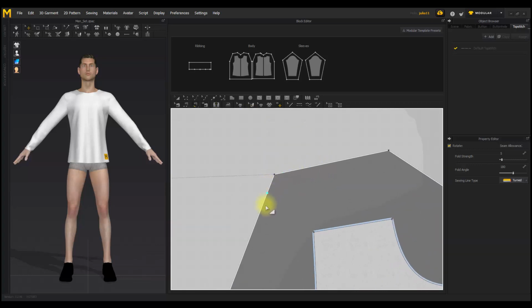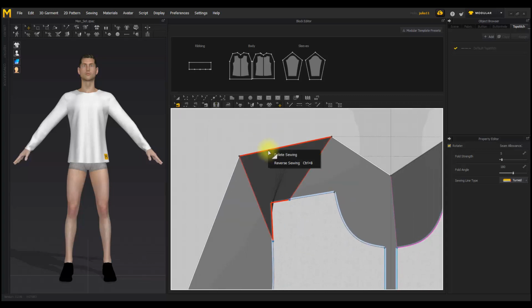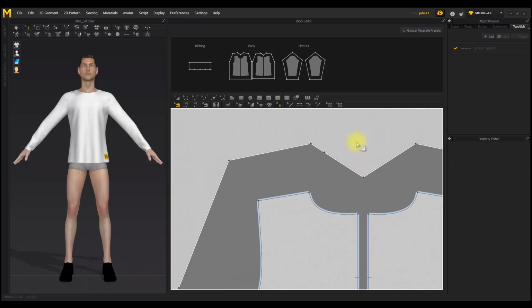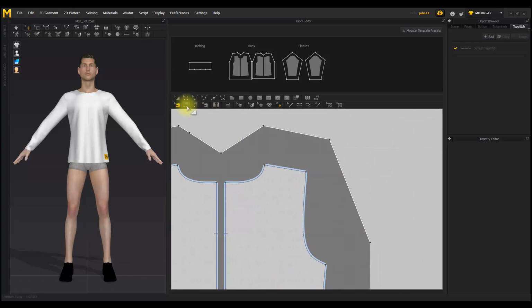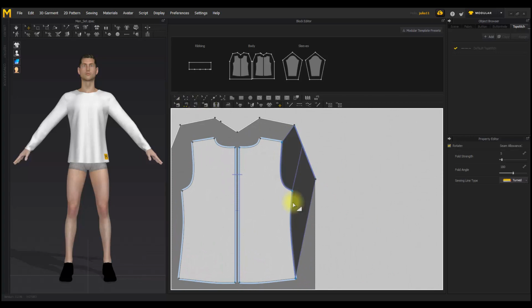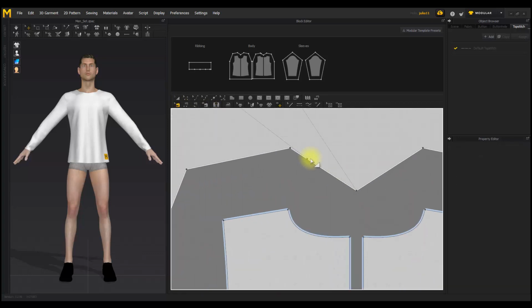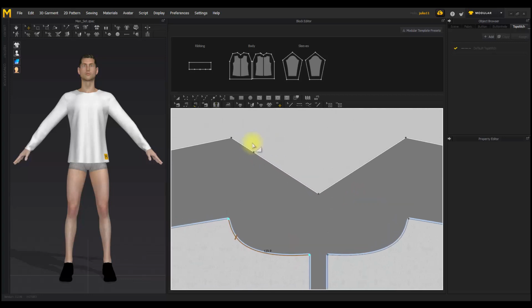Please note, when you sew a block box, you sew by segment and cannot start a sewing line in the middle of the line. It is possible to sew one block box segment with several pattern lines, but you cannot sew multiple block box segments at the same time. Block boxes can be sewn only one segment at a time, and you cannot sew multiple segments at once.